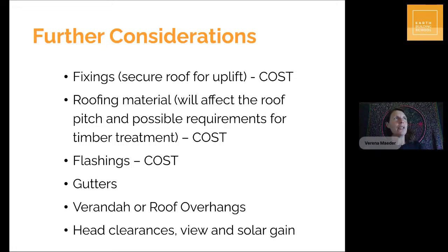The roofing material, as I said, often is sheet metal, so corrugated iron. Lightweight roofs are quite cost effective and low maintenance, and they don't introduce so much weight into your building. If you have a heavy roof, you will have to go to the relevant tables in the timber frame standard.